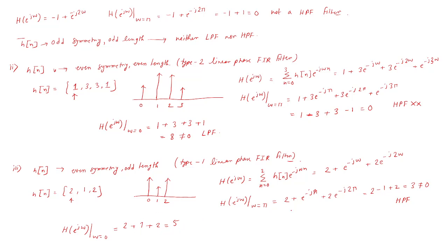Therefore it doesn't satisfy the criteria, since its response at frequency omega equal to pi is non-zero, and its response at omega equal to 0 is also non-zero. Therefore it doesn't satisfy the filter criteria mentioned in the question.